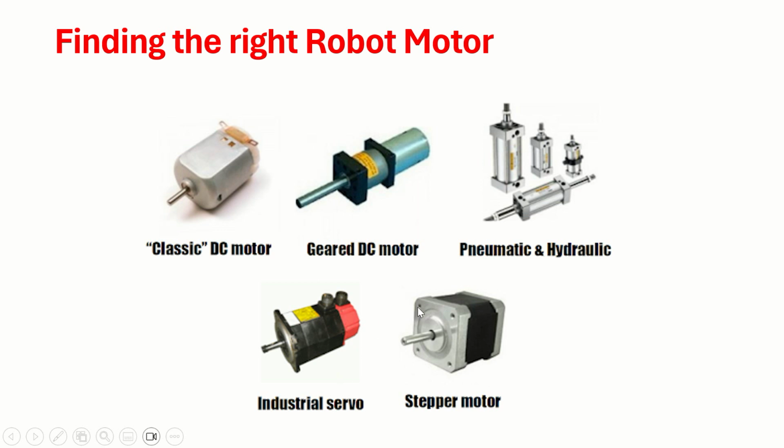However, if we use DC motors, servo motors, stepper motors, they have the advantage of controlling linearly. That means the amount of current which is passing through or the size of the pulse you are generating, there is a correlation between the input and the output. And again, you can have feedback saying that this is my desired value, however, this is my actual measured value.